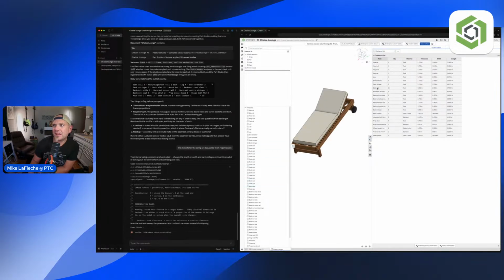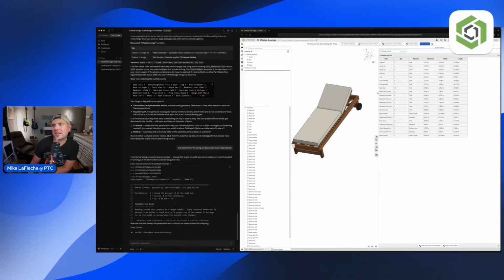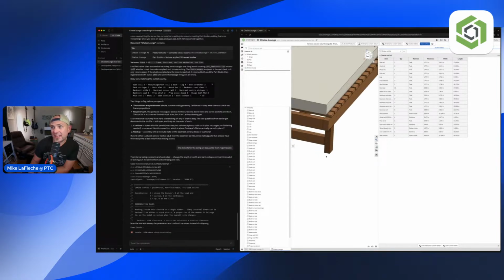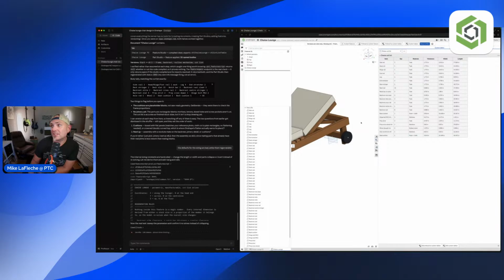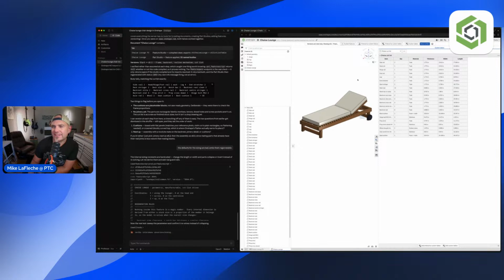But if I just tell the system to create a cut list based on this information with thickness, width, and length, it's even better than the frame tool out of the box because you might have items that don't have frame-based information for thickness, length, and width at a stock size.